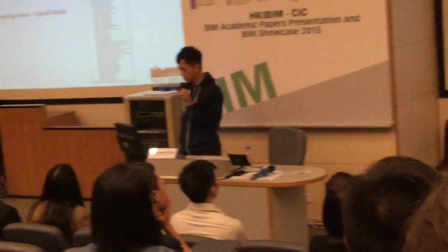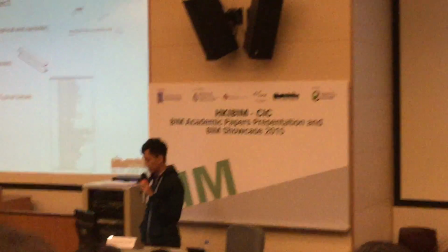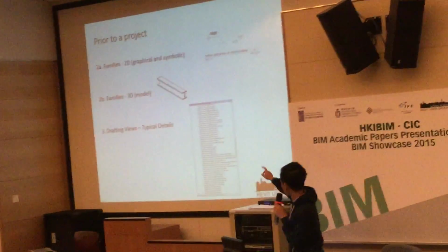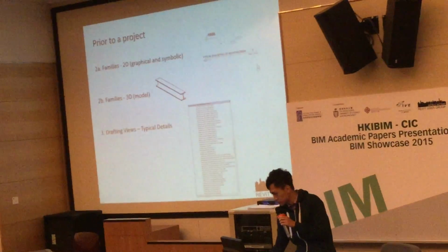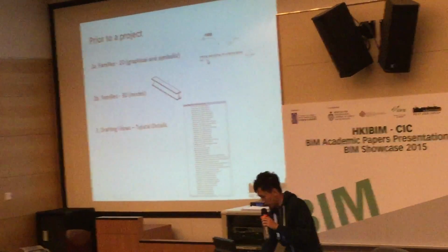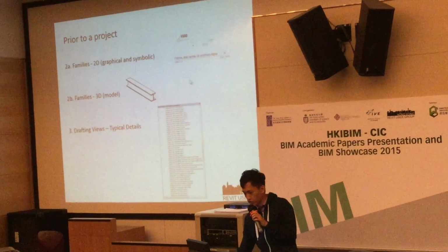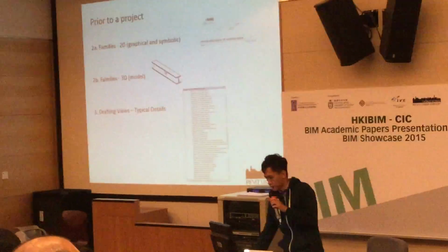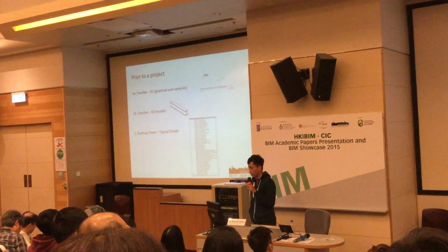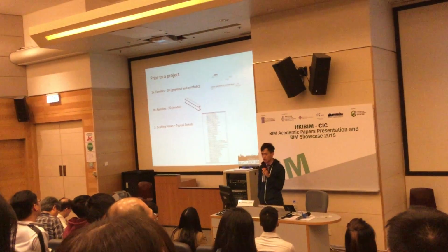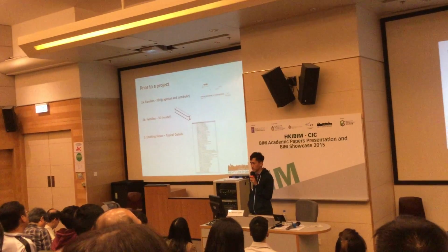So secondly, what you can do is to standardize your Revit families. That will be graphical symbolic, that will be 2D. So there will be something like annotation, drop level there. This kind of title of a detail. And also you've got the 3D families. And obviously for family, you can be really smart or parametric, but you can start with some simple ones.